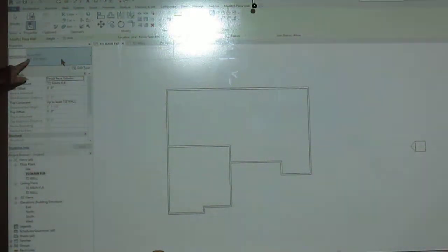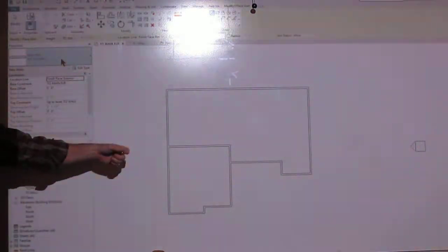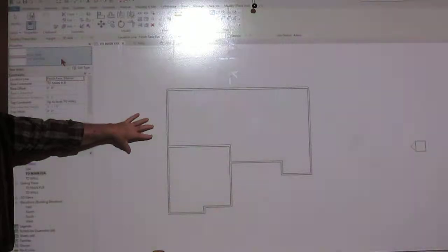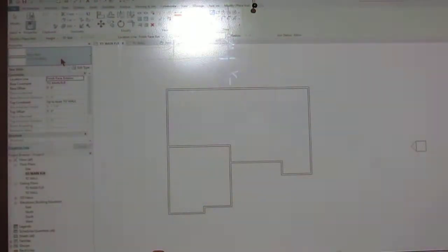Yeah, you should now see interior 2x4 wall, so you should have that wall active. If it's not, use your drop-down arrow, you should see it once you've saved it. Now this is like a block. It's only in this drawing, just like a block in AutoCAD. So it's not going to be available in other Revit files, but you can drop them back and forth.